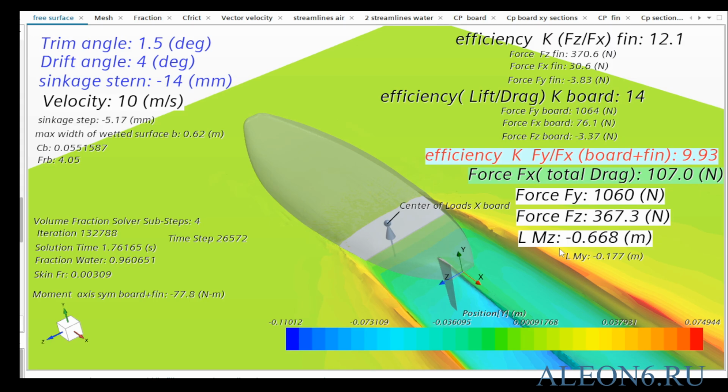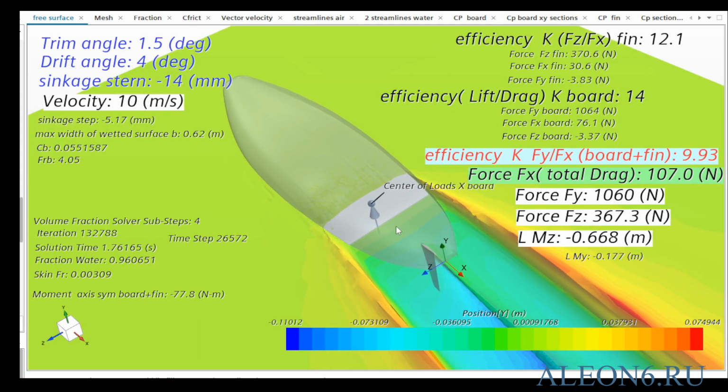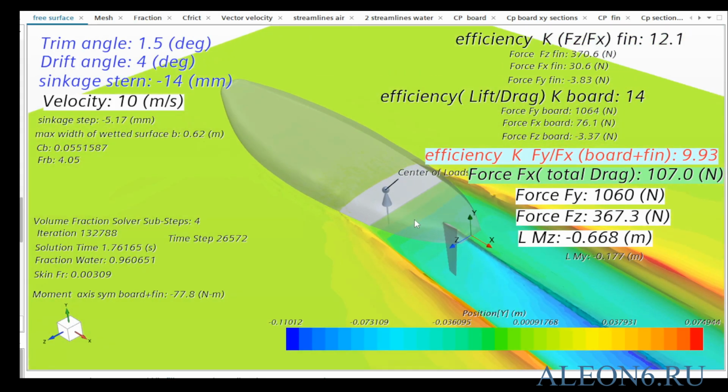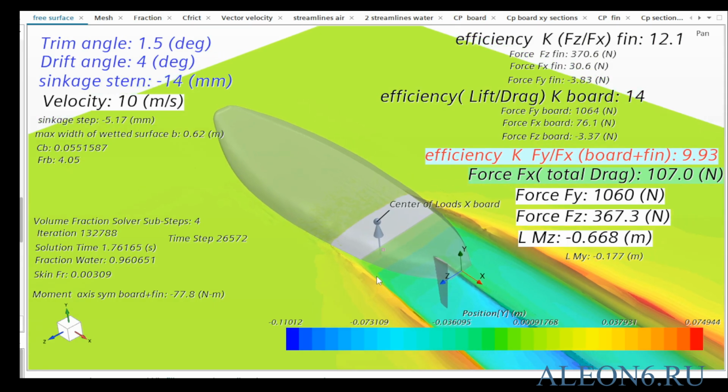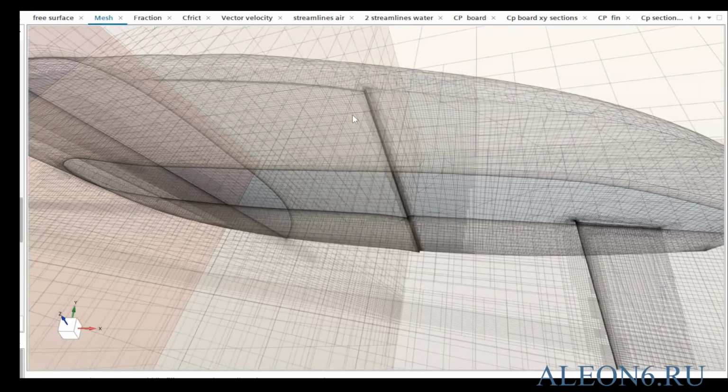The key modification is the introduction of a step on the bottom, shaped as a curved wedge that can be easily applied with putty. It is important to note that a standard wedge could also be used. The optimal location and height of the step were predetermined using discrete vortex methods. The planing behavior of the resulting wetted area, which now has a higher aspect ratio greater than 2, closely resembles the flow around a thin wing.